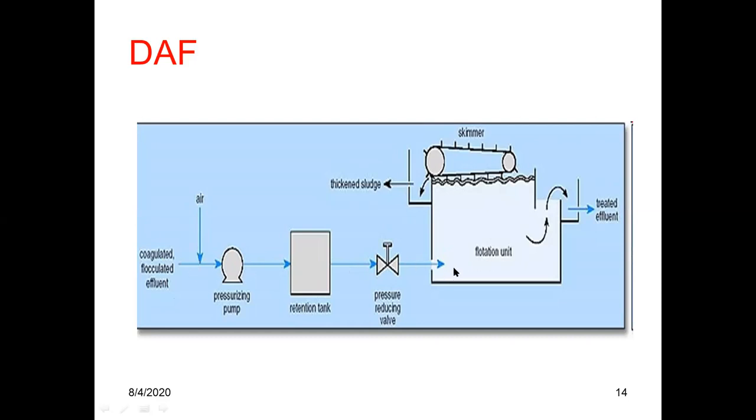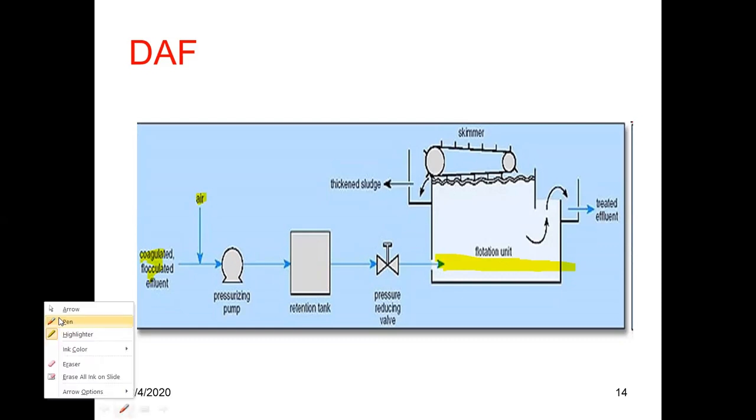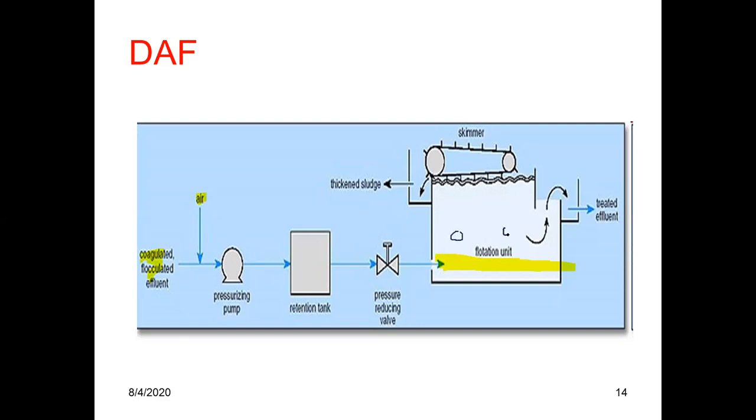Then the water with oil and fat, air, coagulant and flocculant is added into the flotation unit. Because of the addition of air, air bubbles are formed.